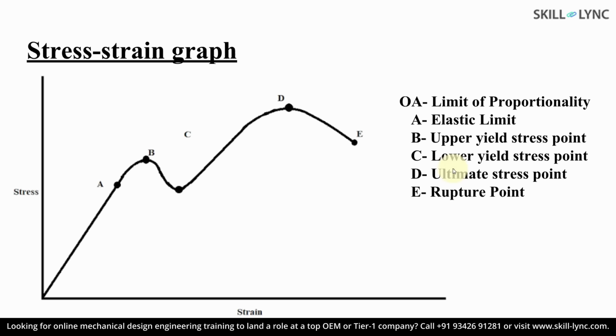This is the stress strain plot for a material. For every model that we use in a finite element analysis, it is going to be made up of a material. Each material will have its own characteristics which are vital for a finite element analysis. To get this stress strain graph for a material, we perform tension tests on the material and plot the strain for the stress developed due to the loads applied.